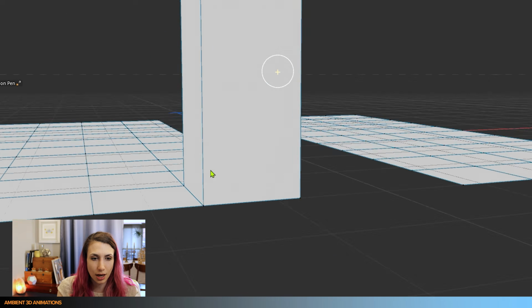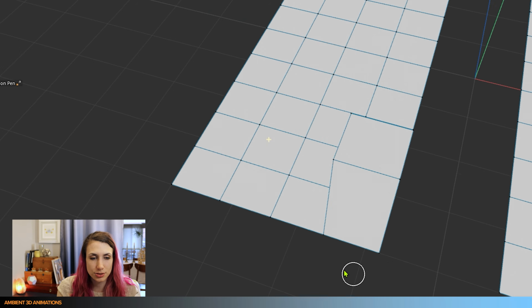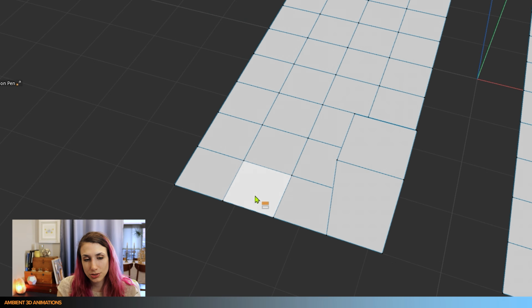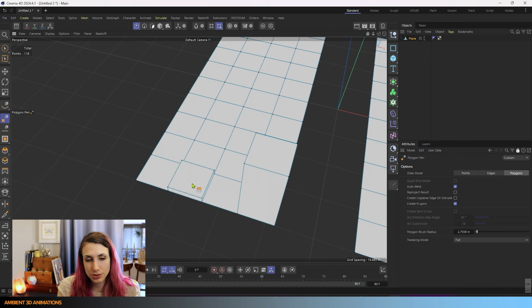We are extruding up, which is really interesting. You can hit Control, click, and drag to extrude again, but this time we'll hold down Shift at the end of that. So I'm not holding Shift, now I am, and we can twist this after extruding it in any direction we want by moving the mouse back and forth.